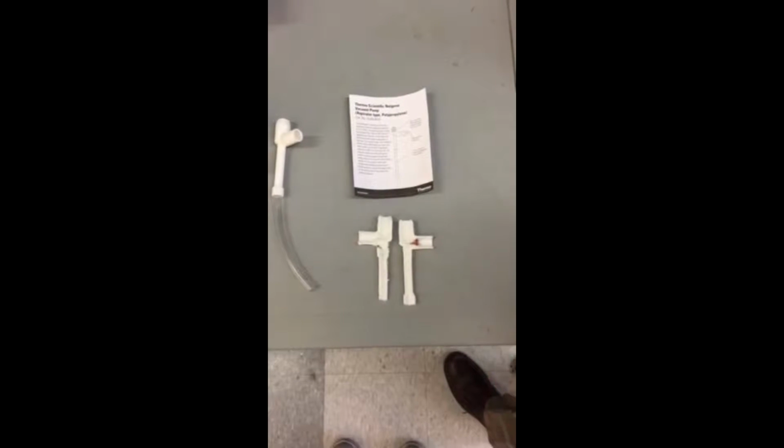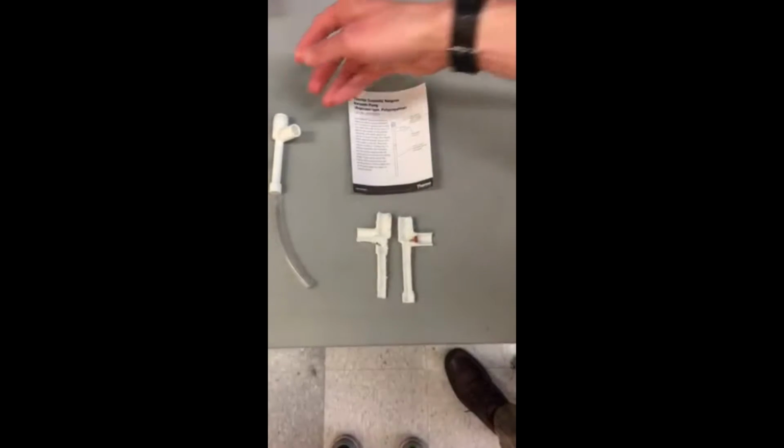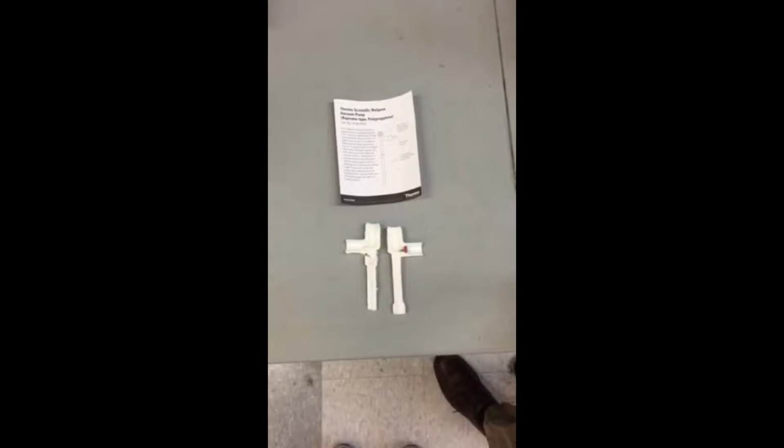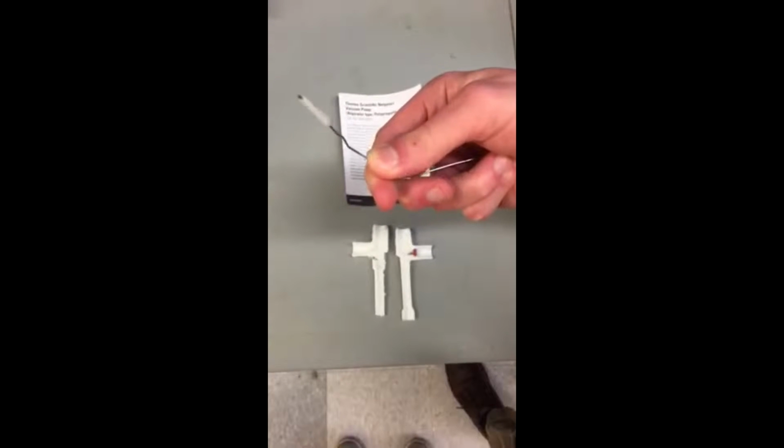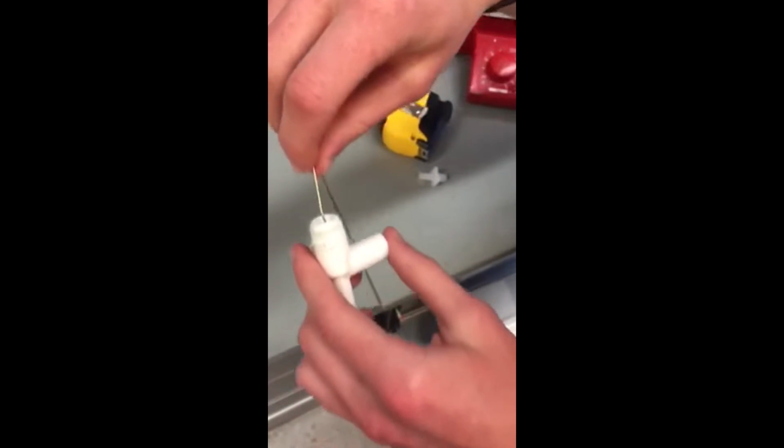Also in this cutout, there's some pieces missing, like a blue orifice where the faucet water initially goes in. You're going to need to be able to measure the diameter of this, and there's many different methods. One of them is to use a setup like this, a piece of metal tape wrapped around it, and push it into a point where it stops, and you can just measure your tape thickness, and that'll get you your diameter.